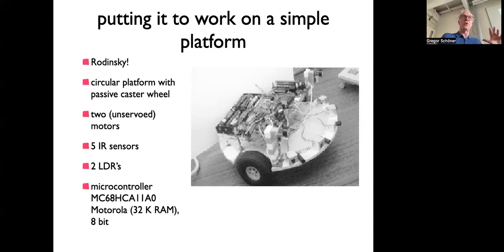That omega is the turning rate, and what you actually need is the current state of omega, which will determine the difference in speed of the left wheel versus the right wheel, and you actually just give some voltage and some factor. You don't know the exact omega, it's just some factor. It has to be close enough, some gain factor. And you also need, of course, to know the sum of the two speeds. That's the speed with which the vehicle goes.